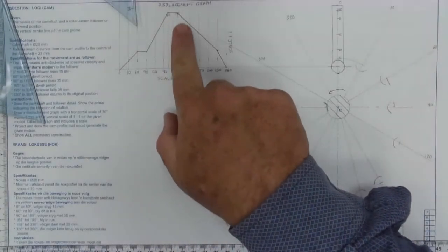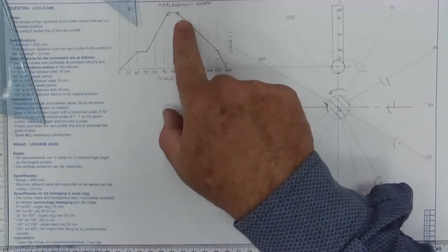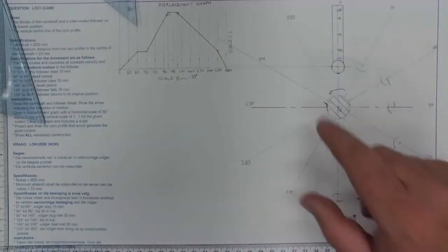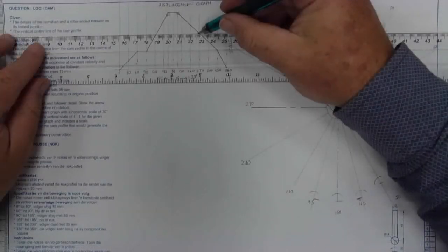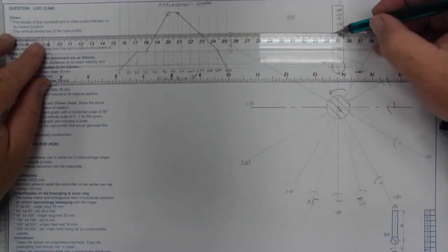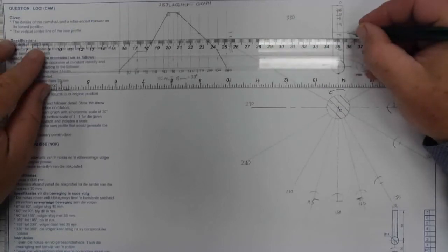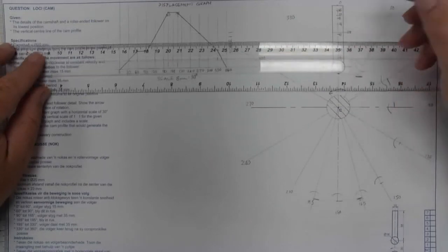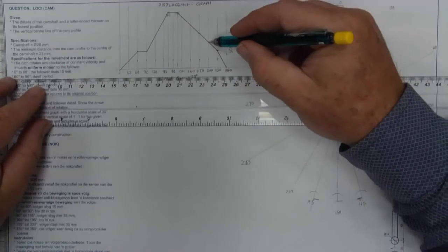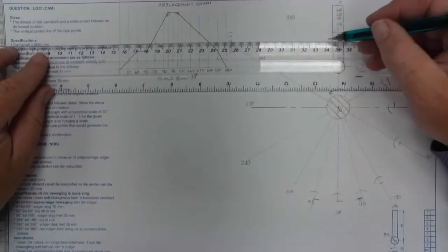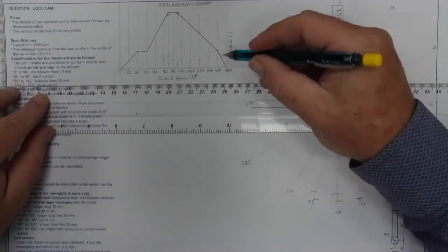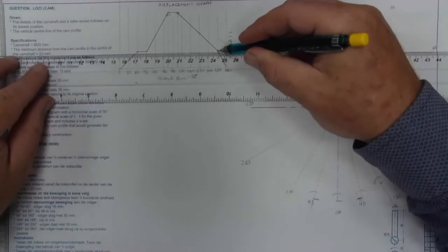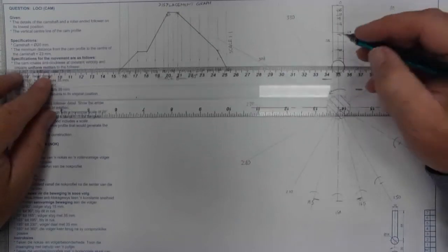I'm now going to come back to my displacement graph and project my remaining points across to my vertical center line. Remember, there's my 270 point. Maybe you want to mark it out here on the side so it's a little bit easier to follow the points. It's really up to you what might work best for you, and whichever method is going to help you get that correct.